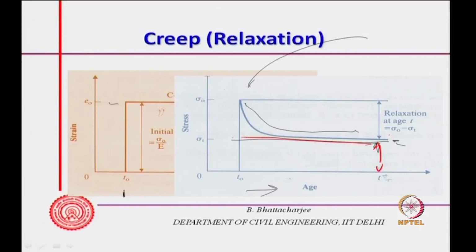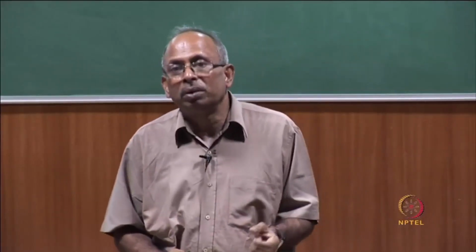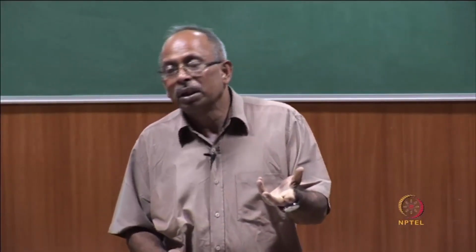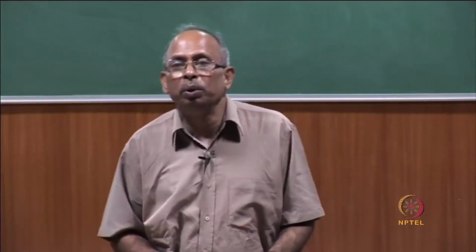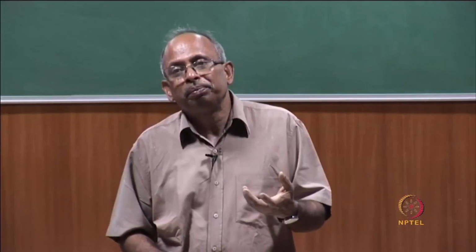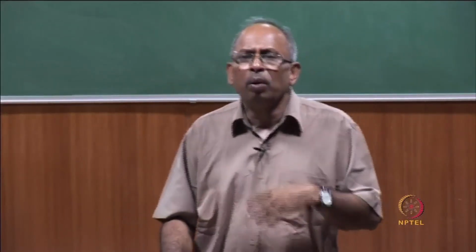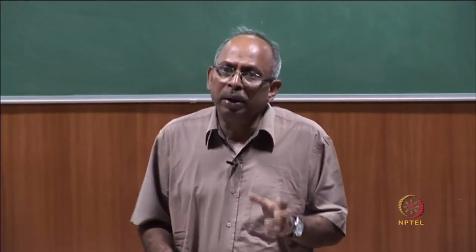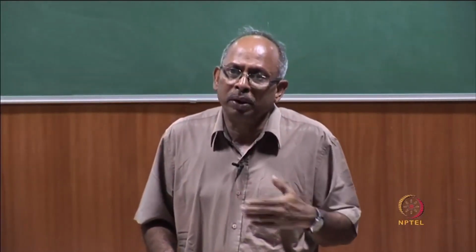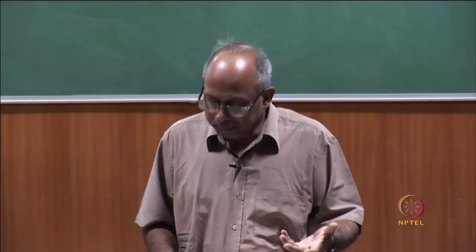So, you see this, if it is a restrained specimen, the stress gets reduced. Through this pre-stressed concrete element that I tried to show you, what I am implying is that this is very important in pre-stressed concrete. We will discuss that sometime later, where creep is very important in certain types of structures, or in situations where creep is important.